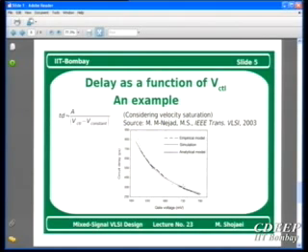For one thing I just wanted to add, just to have an idea: today I told you what was the value in the example. It was a few hundred picosecond per volt as a typical value for the sensitivity, 100 picosecond per volt. See, for the project, as I said, this relation is essentially based on considering velocity saturation in devices, which happens in 0.18 micron.